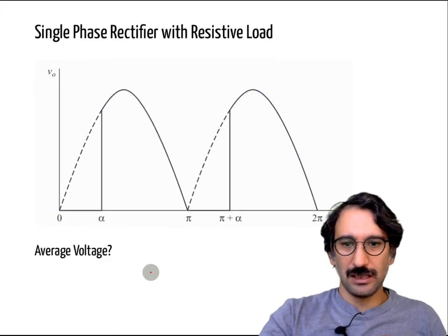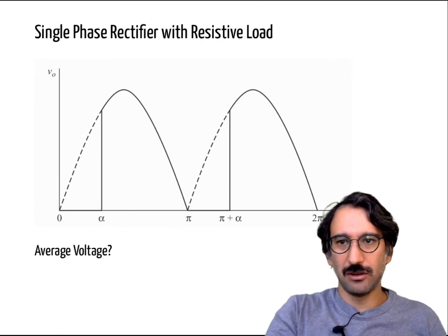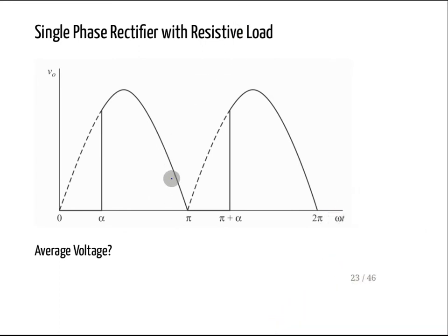So actually, let's calculate it for that one. Here, it is the same logic. I will get that area, right? But in the previous case, I was taking from alpha to pi plus alpha because it was going down to here. But now this part is 0, so I will take my integral from alpha to pi, right? So let me write it here.